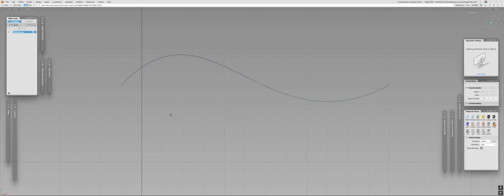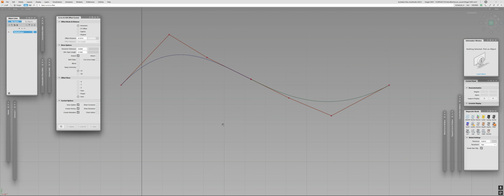And in general, when we're talking about the offset or giving thickness to something, we are talking about the normal direction. So it's supposed to shrink or expand based on the normal direction. It's not always the case. We have options in Alias and the other tools to change the direction, but in general, when we're talking about thickness, we're talking about the offset along the normals. And when we're talking about the offset tool, we imagine that we are moving something along the normals. So let me go in and activate the tool. Now, once again, we're starting with the curves. I will get to the surfaces eventually, so don't worry.